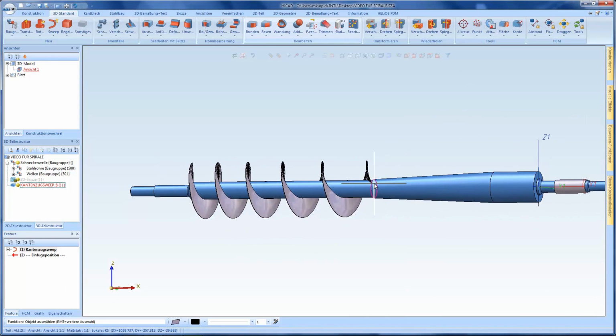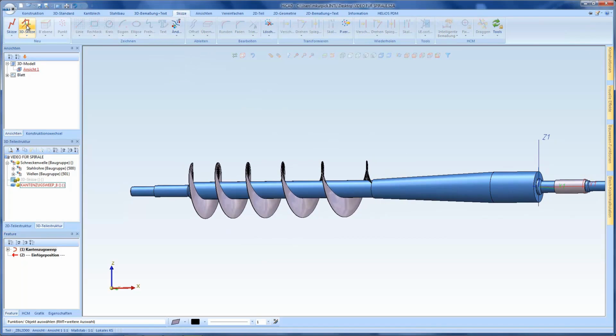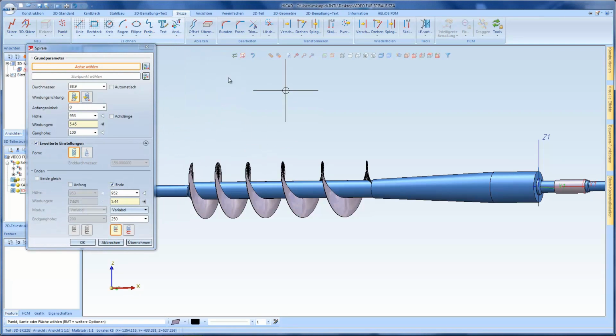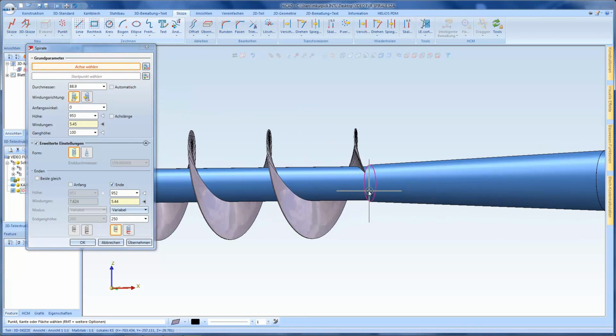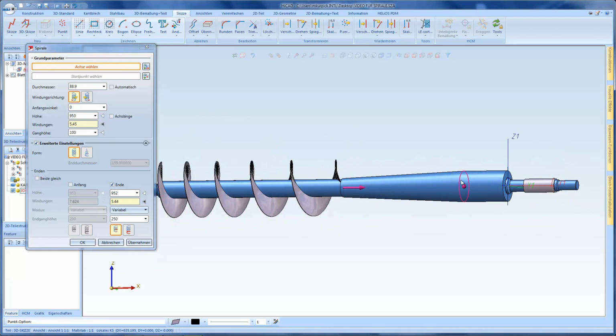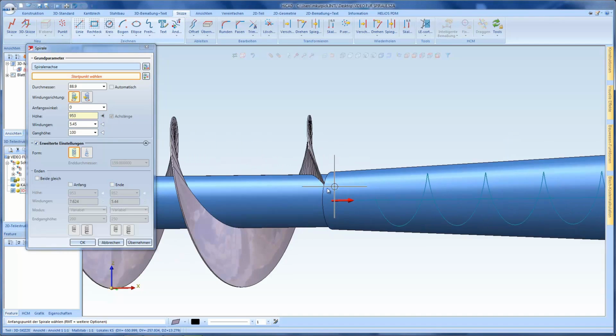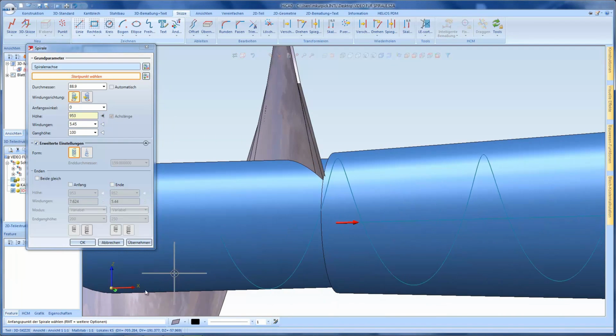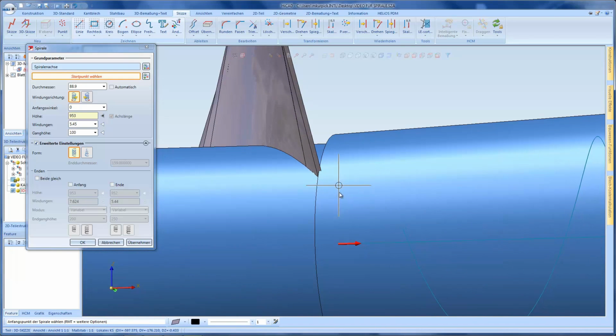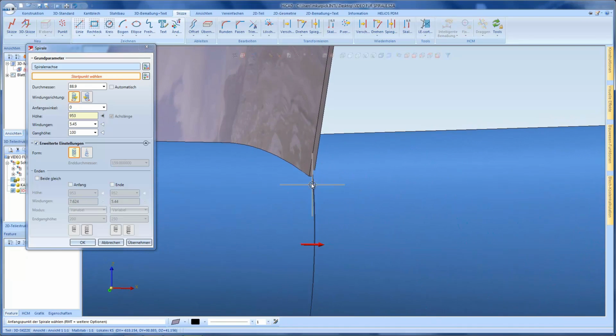The second part is the conical part, which we would also create via 3D sketch. I select spirals again, and I pick the distance from center to center. Axis length is important here. Okay, but first I need to find a start point. Sure. I always have to check the prompts on the bottom left. I surely need the start point, which I have forgotten now.